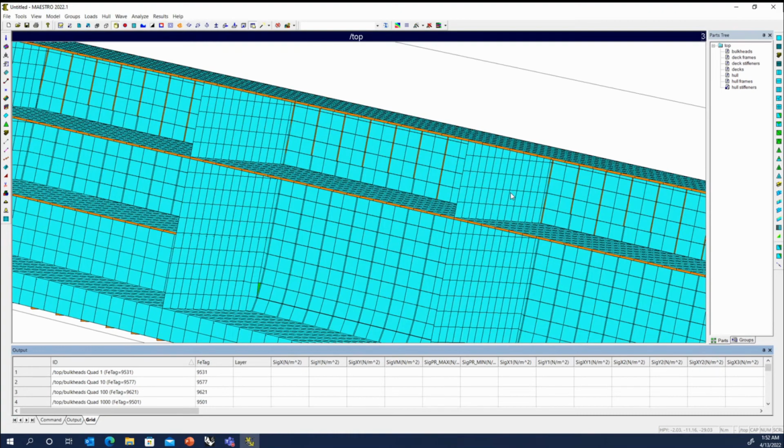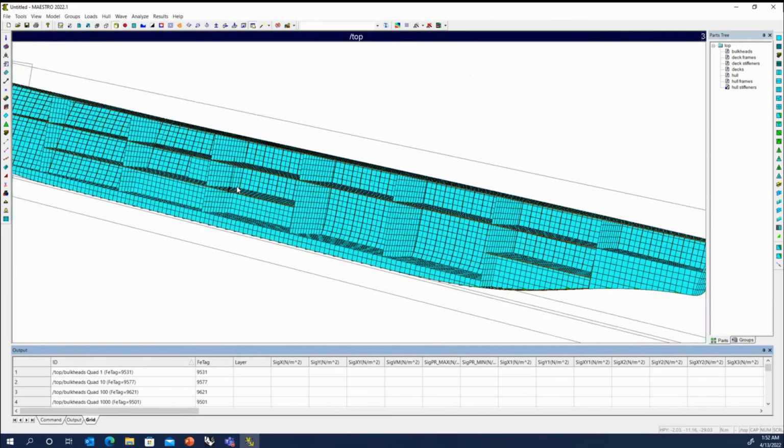That's why when I do this, I typically like to do all the beams on my transverse bulkheads in one export, and I'll do all the beams on my longitudinal bulkheads in another export. That way, when I'm only selecting transverse bulkheads as my reference meshes, I don't have to worry about whether or not there is an intersecting one that it could find the wrong node. So I'll correct the normals on this before I send the model.